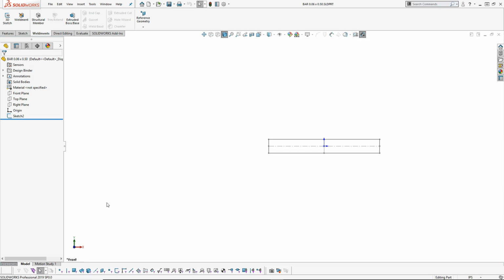In this video, we're going to revisit the library features just real briefly, and then we'll be on into the 3D sketch. So one of the things in creating the sketch, since this is going to be a rectangular profile, I created a folder underneath my Weldments as just bar stock, something that I want to be able to calculate the lengths. A good question would be, why don't I just draw it as a regular extrude? A regular extrude, if it's not applied to the 3D sketch, is not going to generate lengths in the cut tables. So we want to take advantage of that table, so we're going to need this library feature part to maximize.